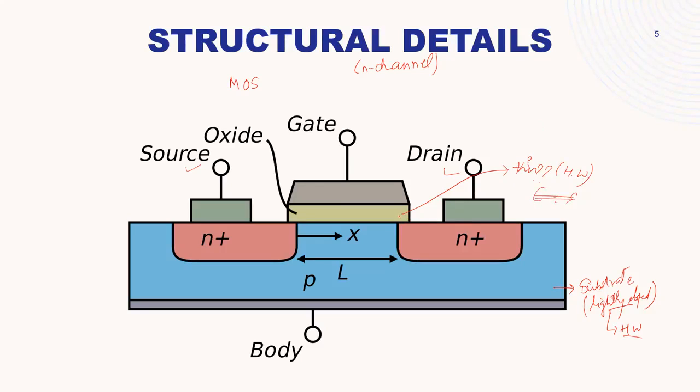So a thin SiO2 layer is grown over the structure through the oxidation process, where this oxide layer will act as an insulator. So the process here will be the oxidation process because we are putting SiO2. Here we were doing deposition. Now, a portion of the oxide layer is removed to expose the source and drain regions. So generally what happens initially, the oxide layer is grown through the entire top.